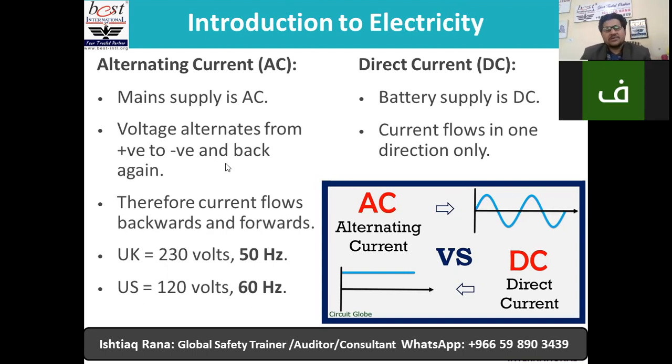In Saudi Aramco, they previously recommended 110 volts for electrical power tools. But now, with an RCD or GFCI for 110, and a residual current device with 220, that is what they recommended. Mostly now they are moving towards 110 in most areas, but I noted several areas still using 220, and it varies according to need.